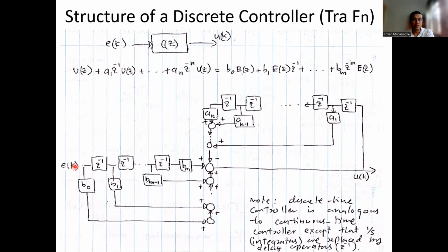The error signal is coming from outside as a voltage signal, and you want to take that into the microcontroller through one of the digital pins. Or you can connect the analog error signal through an analog to digital converter in the microprocessor. You read it. Once you read it, what does this z^-1 mean? A time delay.